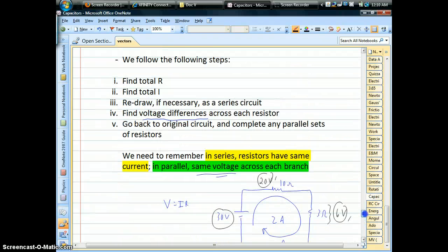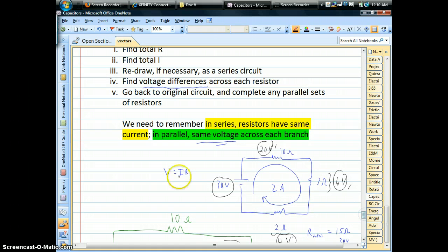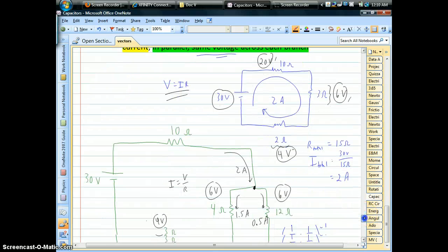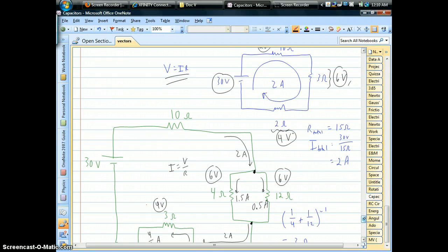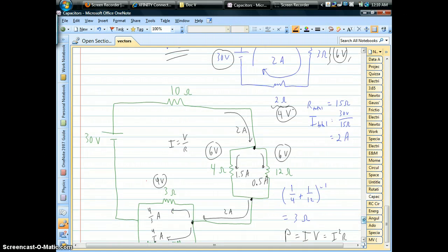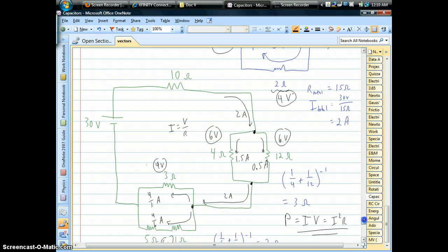We used just a few little steps here, just a couple rules. We've got Ohm's law, and V equals IR. We've got the 2 Kirchhoff's rules. Voltages add up in series, currents add up in parallel, and we know how to find series and parallel resistances. With those small numbers of rules, we can figure out pretty much all of these different types of circuits with resistors.